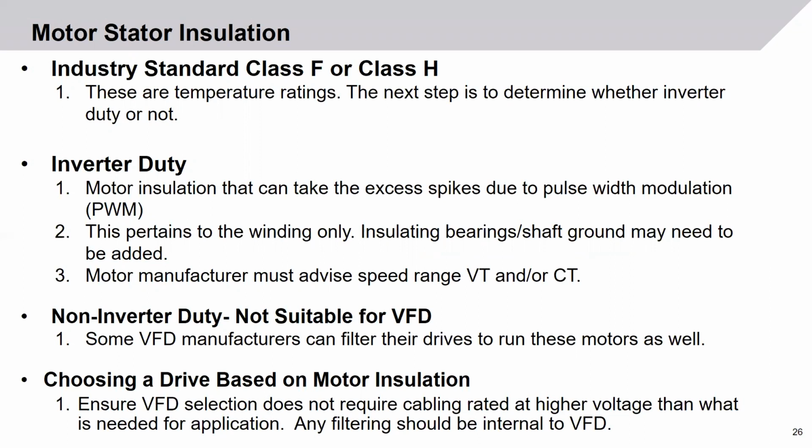How to choose a drive based on motor installation. The most important thing to really look at is to make sure that the VFD selection does not require special cabling or special external filtering that is rated at a higher voltage than the application to filter before the motor. Any filtering should be done internal to the VFD.